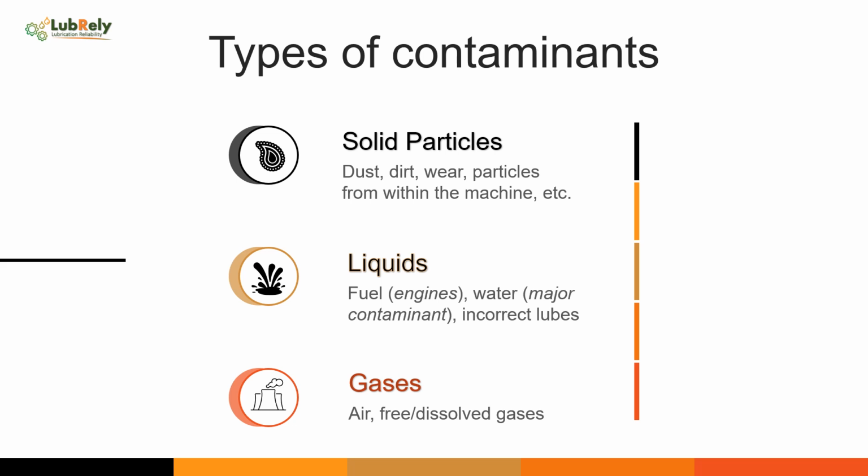Air is not particularly damaging, but the air contains oxygen, and the oxygen can cause oxidation. So pulling the air out of the system increases the life of a system. So, how much contamination a system can tolerate depends a lot on the system itself, and some systems are going to be having much more need of cleanliness than others. It all comes down to the cleanliness involved in the components. One thing is for sure. All contaminants in the lube will affect the life of the components.